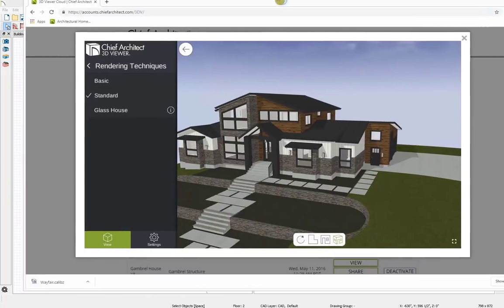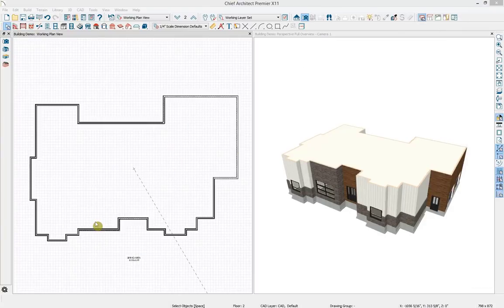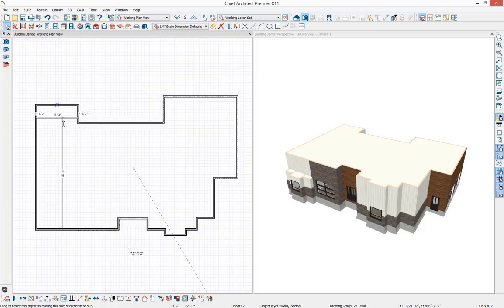And now let's take another look at the house, the finished version. So you can see we're not going to be extending all of the walls up to the second floor, so we need to modify these walls so that it's just the interior section. So what I'm going to do is I'm going to just start pulling walls back. Basically get rid of all of our bump outs. And at some point I'm going to need to turn on my reference floor display.